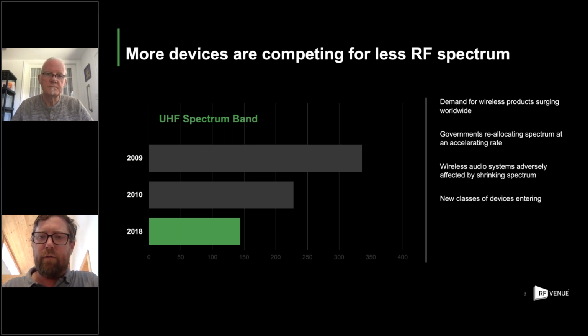And then there's the looming boogeyman of new classes of devices entering, be they 600 meg band mobile devices, or white space devices, or whatever may come down the pike as things change. So whereas some years ago you could set up an 8-channel, 12-channel mic system, push your easy button on the front of it, sync them all up, fire it up and be ready to go, that is not really what things look like anymore.